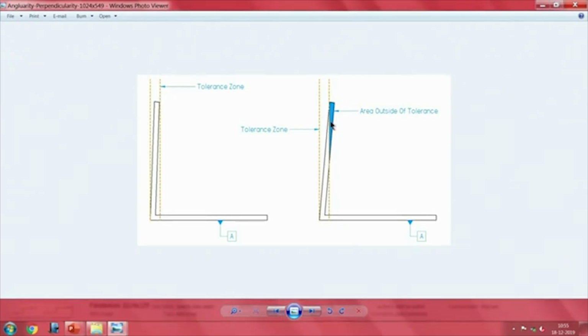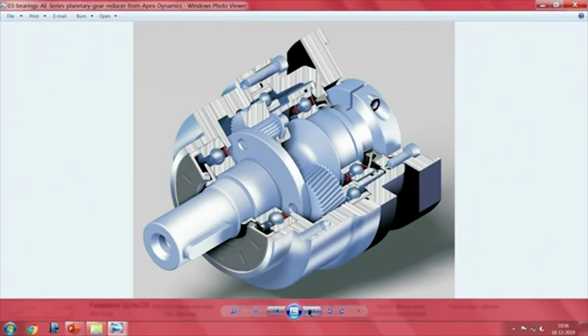This is the tolerance zone, something has fallen out of sight. Imagine somebody makes a part, one end follows one edge of it and another end follows the other edge of it. Will you still accept it or not? This is where things like perpendicularity and parallelism are stressed regularly. And the magic is, a simple solid model very rarely seems to take care of these things. You got my point? Why I specifically picked on this is that a simple solid model makes something which looks exotic, but in practical operation, depending on the processing and all that, one needs to work carefully towards how these things actually work.